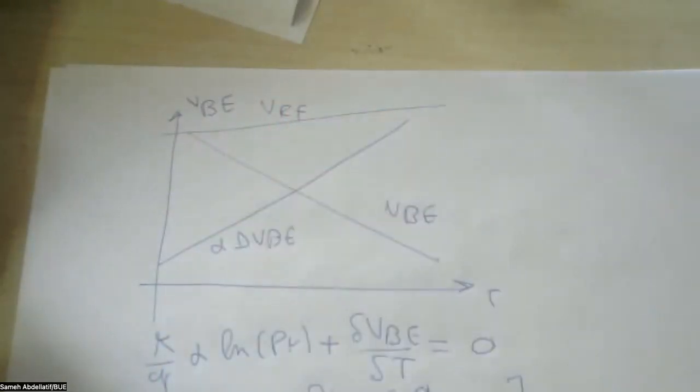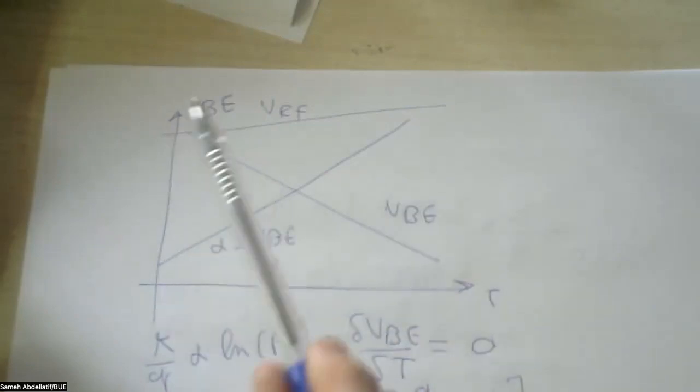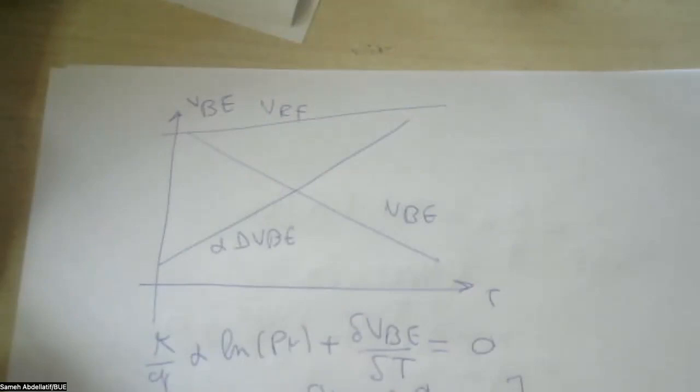So the process of creating the reference voltage is simply the process of adding two elements. Each of them is temperature dependent, but in a reverse manner, so that the summation of these two terms ends with a constant. Let's see this on a graph.